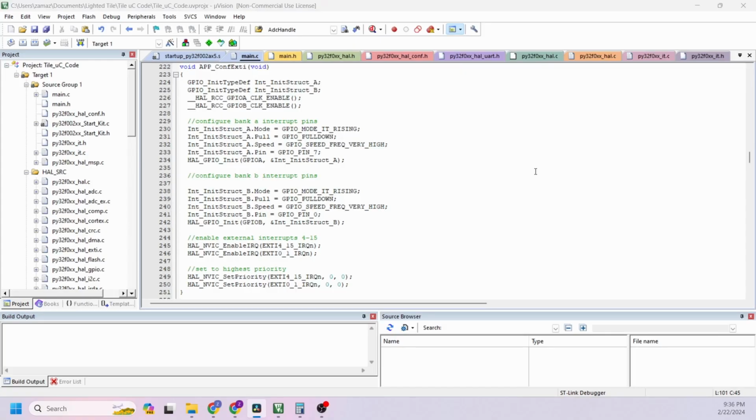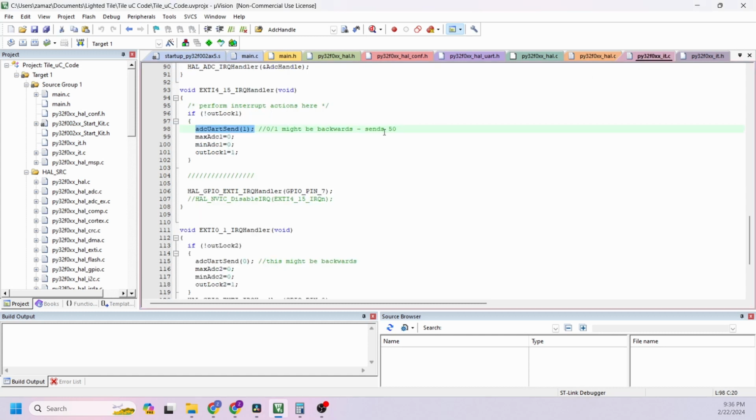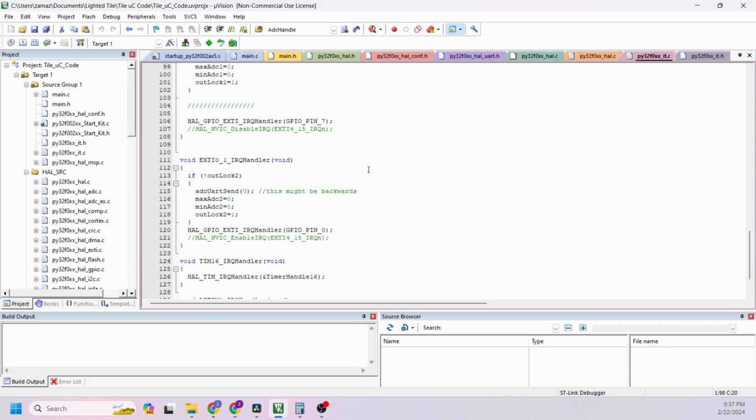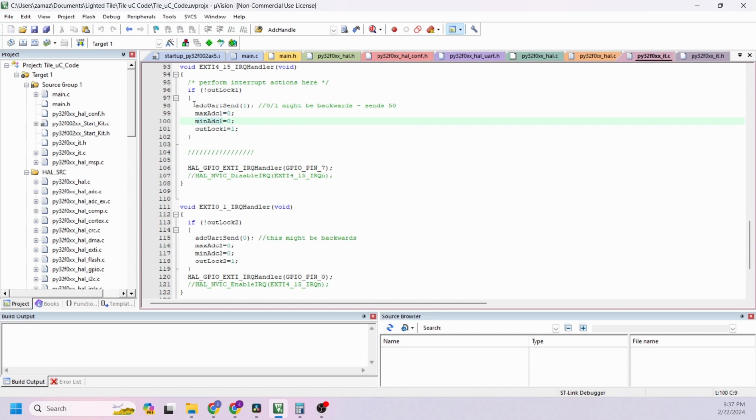To get the microphone amplitudes out of the PY32, I implemented two external interrupts. One of these watches the signal input to the first LED, the other one watches the signal input to the second LED. As soon as the microcontroller sees the voltage go from low to high, it jumps in the code over to a portion that sends the appropriate values back to the main controller. It's pretty simple. Just send the saved amplitude over the UART.